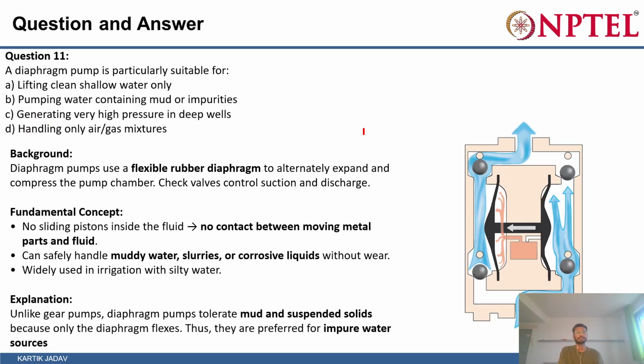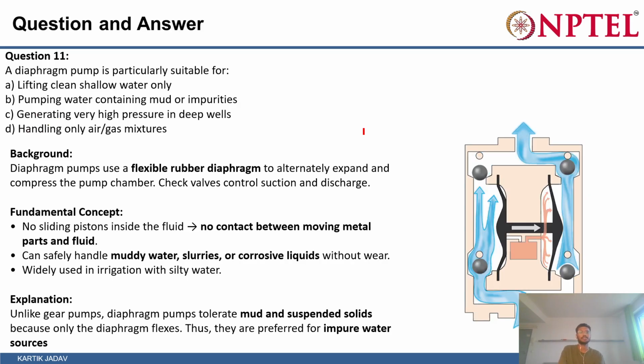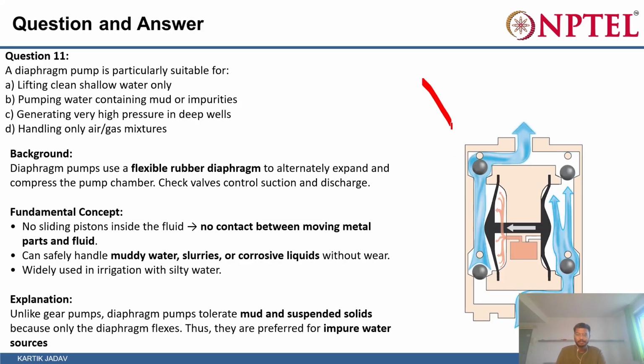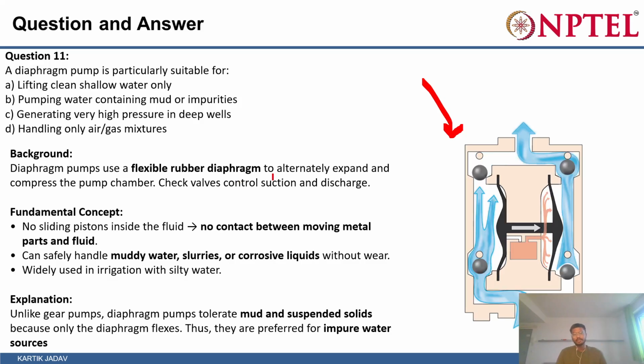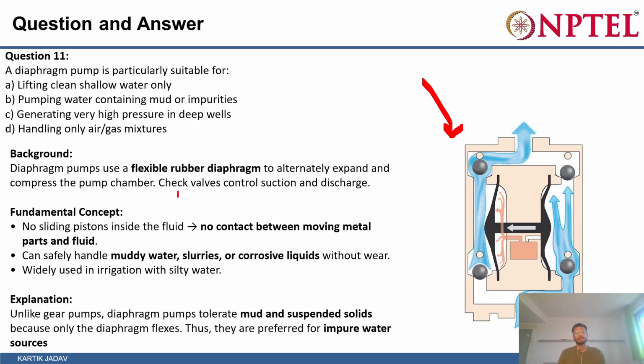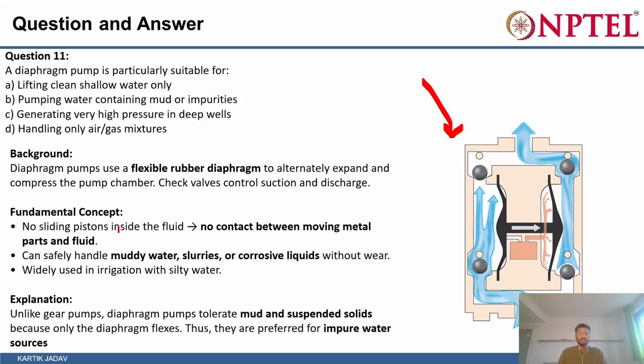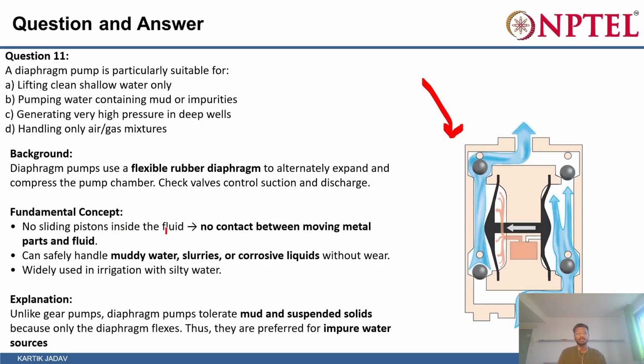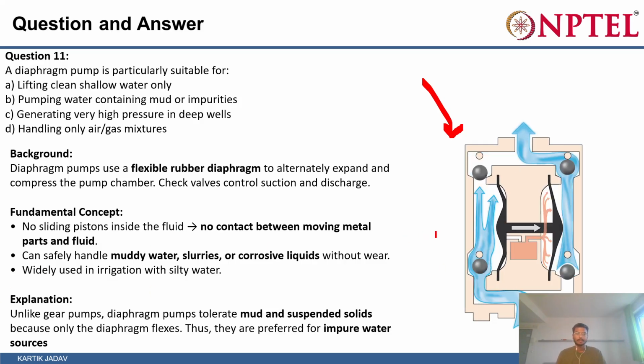Question number 11. Diaphragm pump is particularly suitable for. So we know that this diaphragm pump uses a flexible rubber diaphragm to alternately expand and compress the pump chamber. And check valves control the suction of fluid. So you can see the fundamental concept is no sliding pistons inside the fluid, okay,